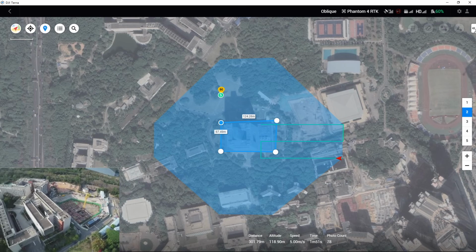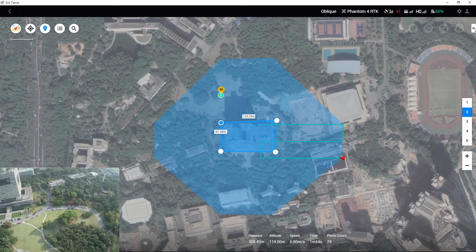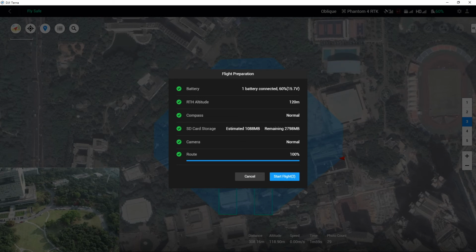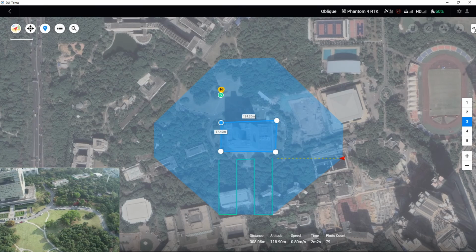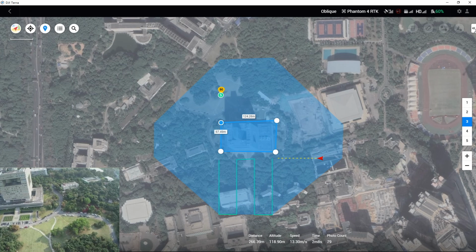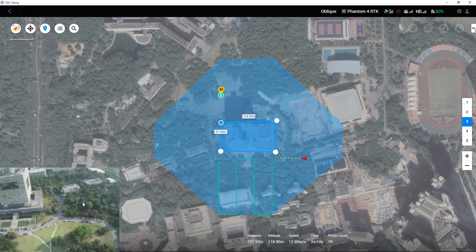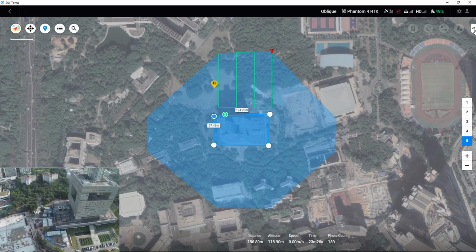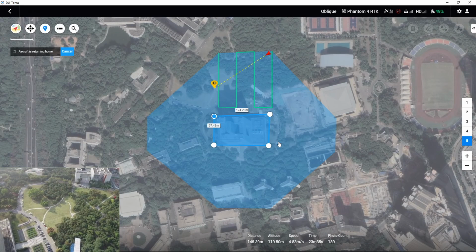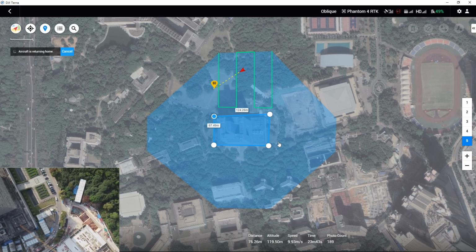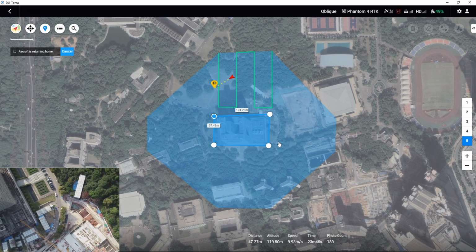When performing the first to the 4th missions, if the connection between the remote controller and aircraft is strong, DJI TERRA will automatically upload the next route information and carry out the next mission after the current one is completed. If the aircraft and the remote controller have been disconnected, the failsafe RTH will be activated after the current mission is finished. After the 5th task is finished, if the connection between the remote controller and the aircraft is strong, the aircraft will perform the preset completion action. If the aircraft is disconnected from the remote controller, the failsafe RTH will be activated.